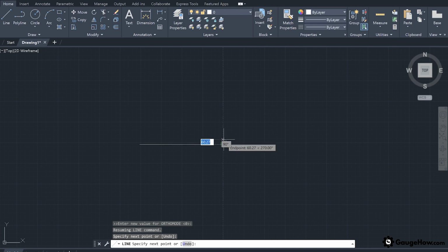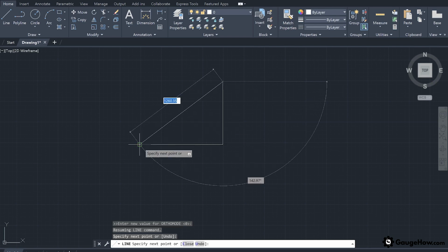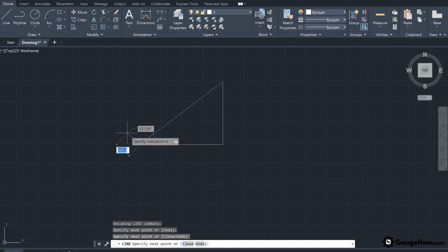Again, if you want to draw the vertical line in upward direction, then again you can hold the shift key and move your mouse in upward direction. And you will see that now only a vertical line can be drawn. Now you can manually close this figure also by joining the starting point and the end point and hit the escape button. So these are the different ways that you can use this line tool. So I hope you found this use of line tool very easy at the starting point of your 2D drawing.